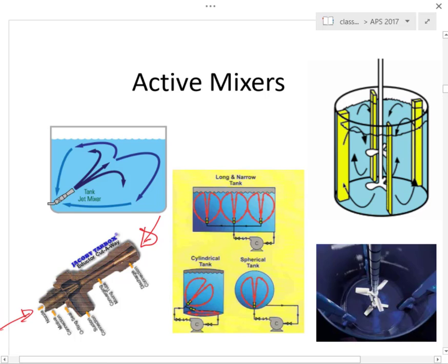If you have flow that goes in like this, and it goes through, see, this is a little nozzle right here, and then there's an open space. So this is open right here. This forms a jet that shoots out, and the jet is exposed right here. You have a very high velocity jet that creates suction, and so that pulls fluid in like this.